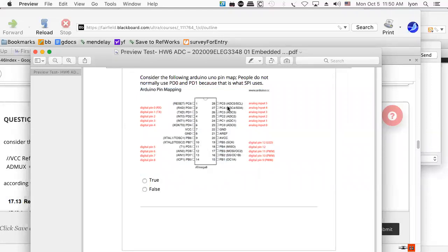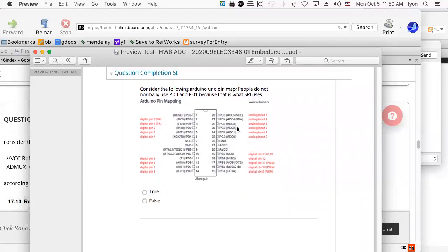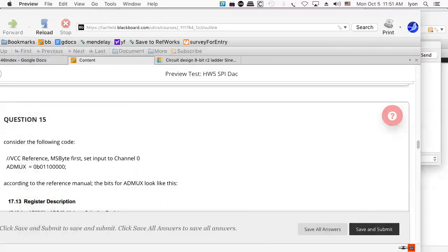This is a dual inline package. Most of the time, unless you're using the shop-based Arduino Uno, the one in the lab, you're not going to be using a DIP. You'll use a quad leadless chip, and it's a surface mount device. So then what you look at in here, you say, geez, it looks like 6 A to D converters, but it's not. It's multiplexed. And so I have an A to D converter multiplexer. And that's the reality of having to program this thing.